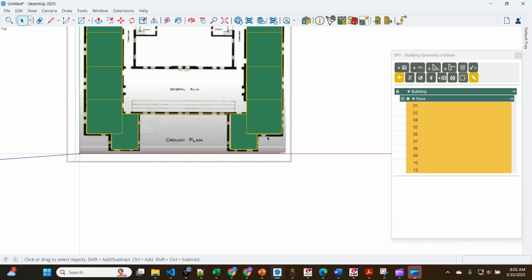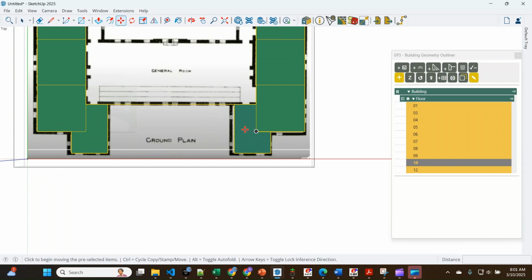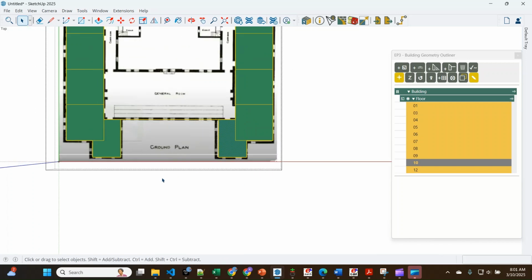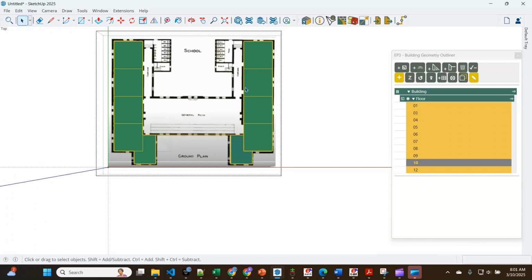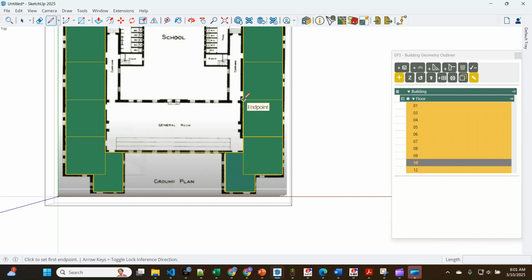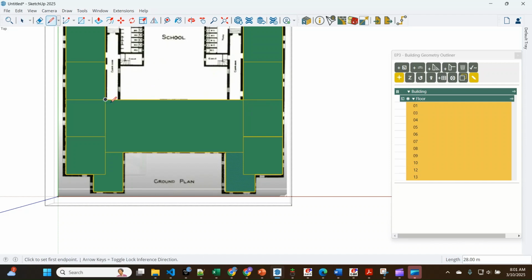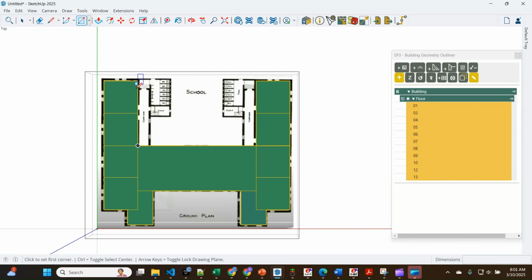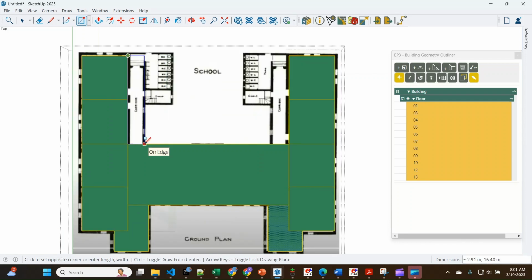SketchUp has this thing where, once you've attached a surface to another surface and then you move it, it's kind of sticky, which can be fun, but it's not great for architectural drawing. So if all of your geometry is in one place and it's all sticking together, it makes it quite difficult to redo anything and change just one little piece.